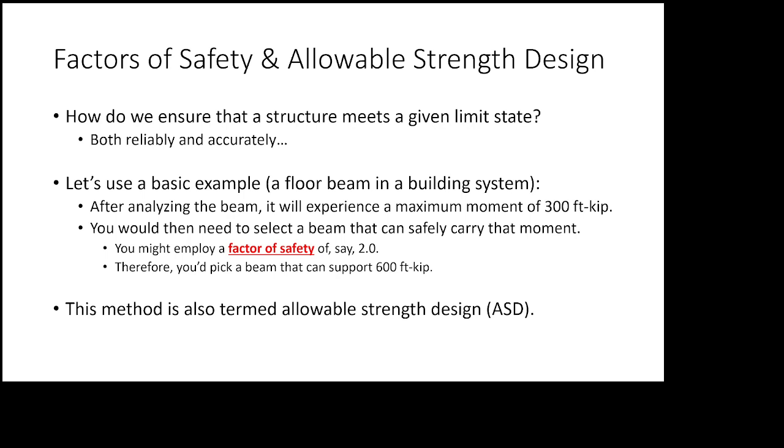What do we put on the roads in February in the state of West Virginia? Salt. What do you think salt does to steel and concrete decks and what have you? Causes all sorts of corrosion and whatnot. So we have conditions that we have to meet. The reinforced concrete engineers like to use cover requirements, right? The rebar has to stick some amount in between the surface of the concrete and inside.